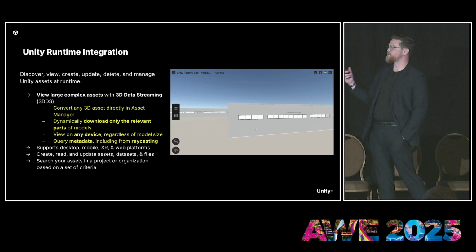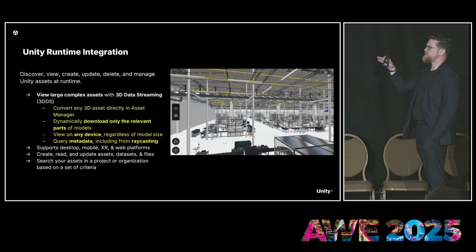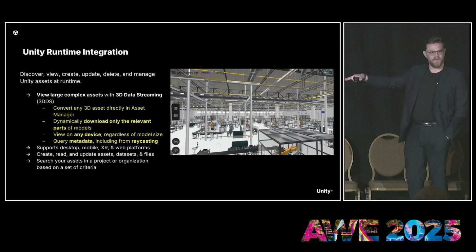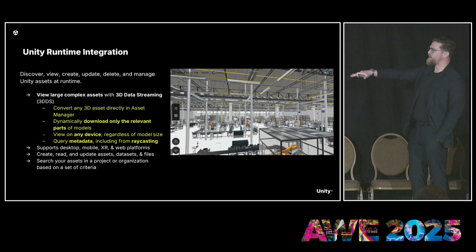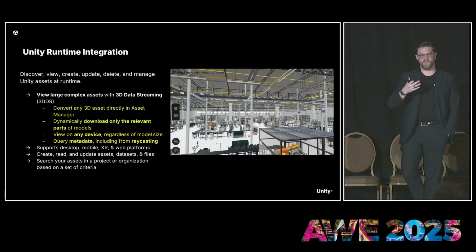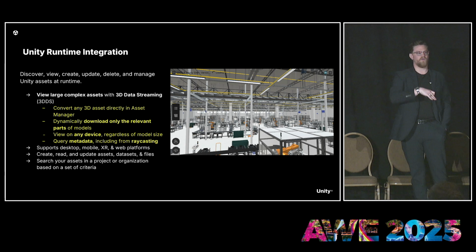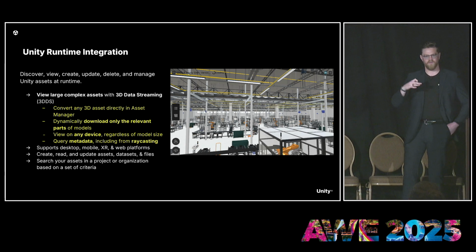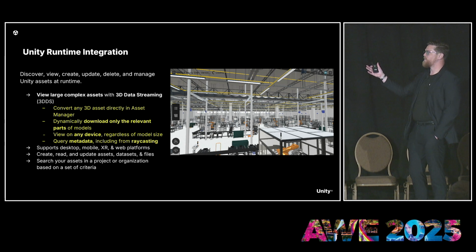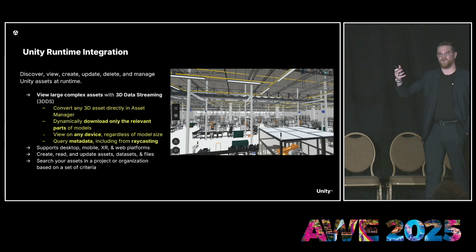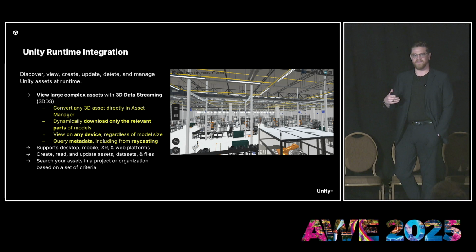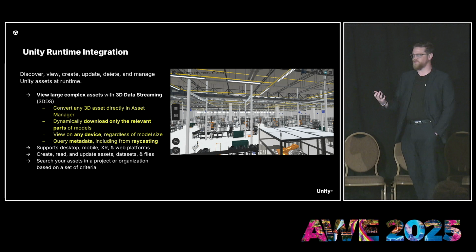So what we're looking at here is we're going to zoom in through the window and see a bit of how the tech is working on the back end, which is you can see some of the LODs loading in. So as we pause the camera, the fidelity increases. You can think of this technology almost as a combination of geospatial 3D tile mapping and hierarchical LODs, if that makes sense. So there's a bit of a combination there of the different technologies. And effectively, that's why we're able to show such massive, dense models, is because they're all fragmented into minuscule pieces that we can up-res and down-res as is appropriate to the viewer in the camera frustum.